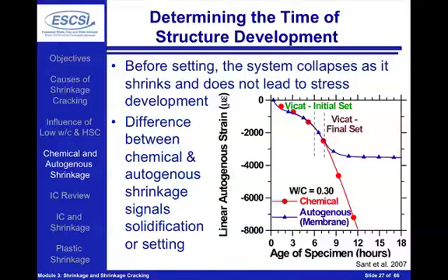a capillary pressure inside the system. We're going to start to build up this under pressure in the fluid, and we're going to start to create these vapor-filled spaces that we were talking about before. So all of a sudden these pockets of vapor are going to start to expand, and that's really what's going to give rise to this concept of self-desiccation.